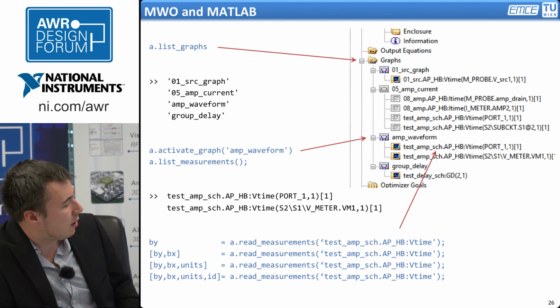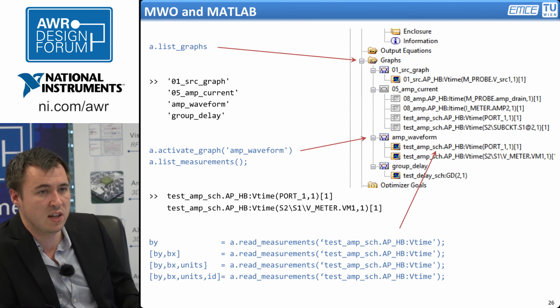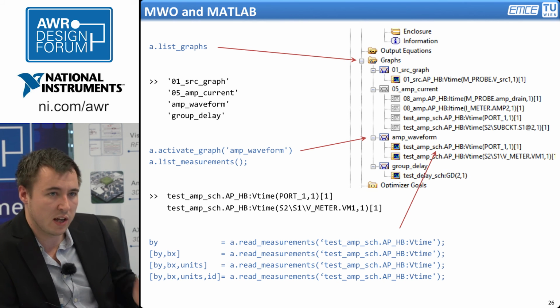And this is the only thing where we have performed a bit more elaborate implementation, since these always are very lengthy names and we are somewhat lazy people. We're using regular expressions here, so you don't have to type in the full name, so you can just use an identifier that is long enough to specify which graph you really want to have, and then you can have only the y data points, the complete list of xy pairs, or you can also get the units if it's for whatever reason important for your software to see if these are voltages over time or whatever.